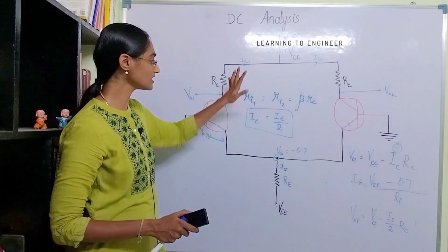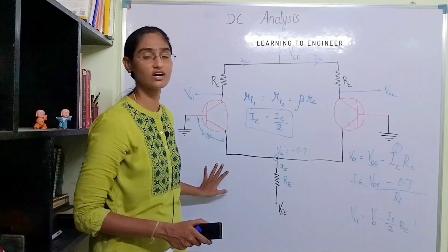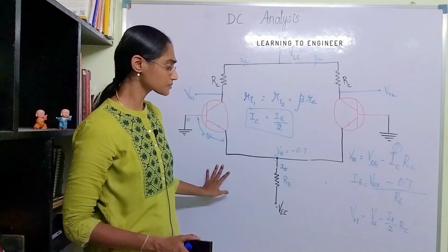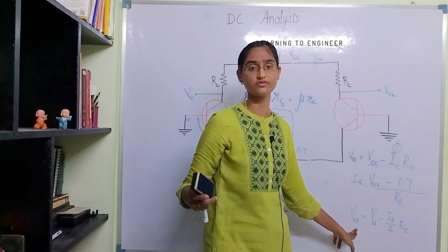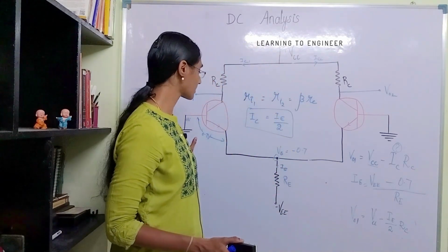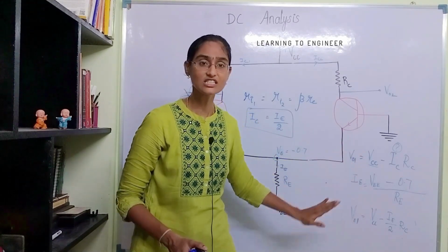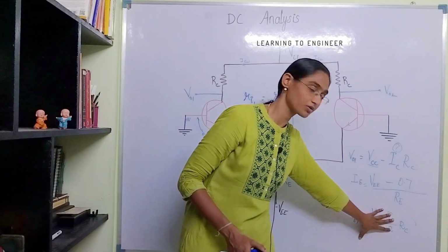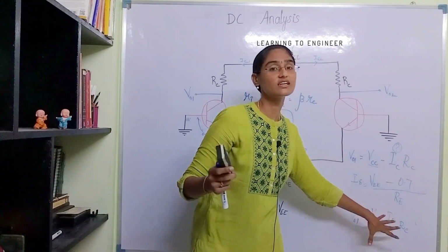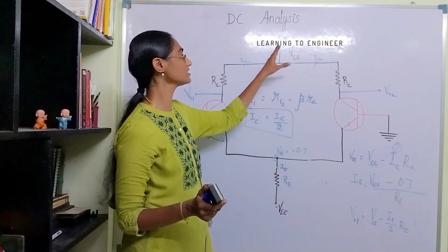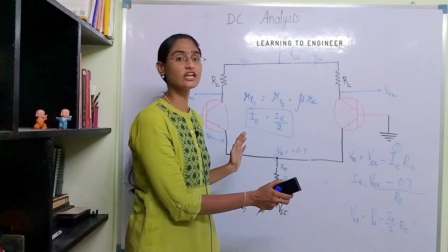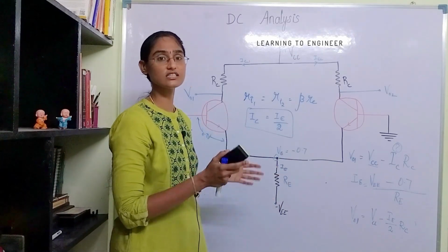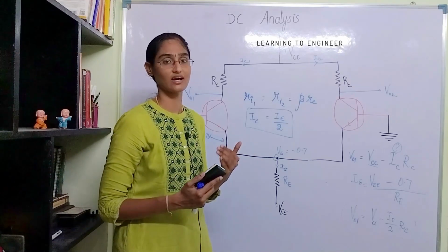Okay, so this is the DC analysis of the operational amplifier. This is the output that is occurring purely because of DC. When we have 0 volt connected to both these terminals, this will be the output, and this output is because of the DC operating supply. Okay, so I'll just clear the screen and we'll analyze the circuit with respect to the AC parameters.